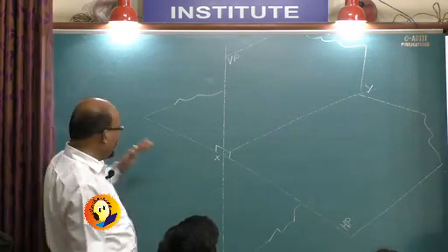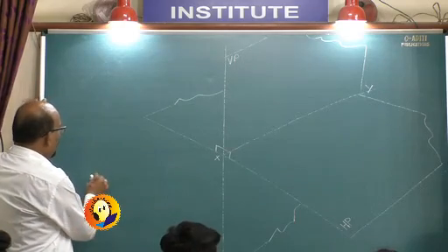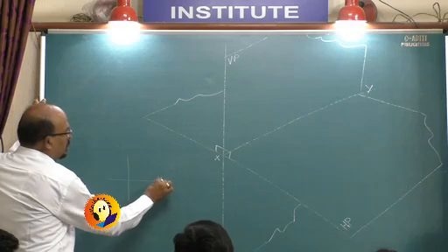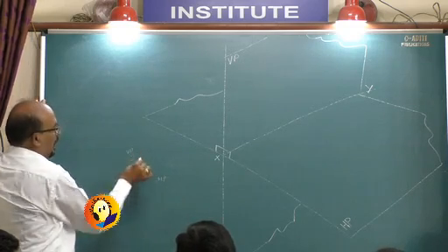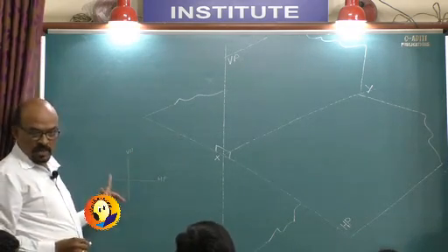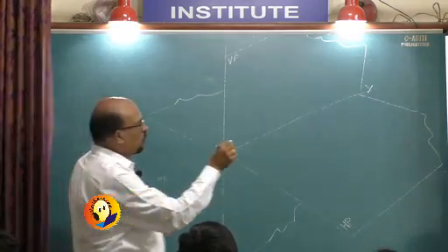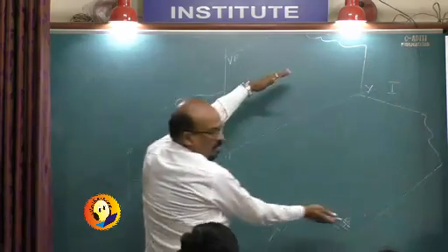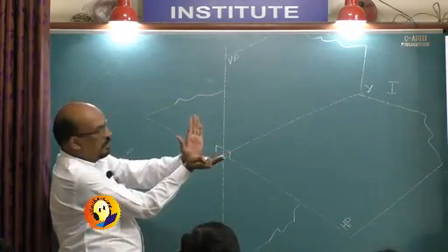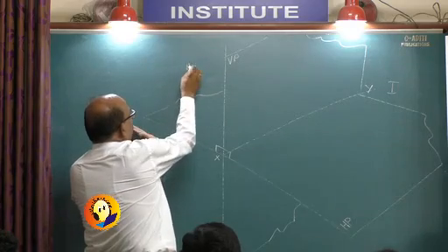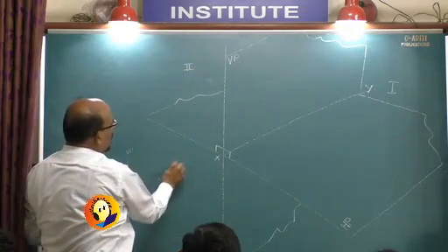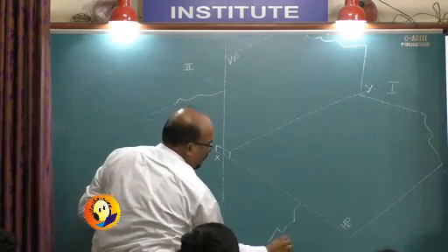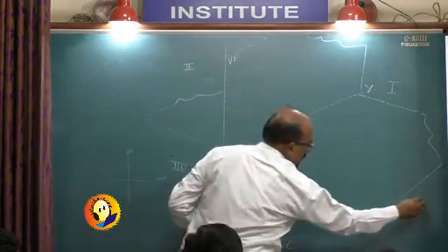Got this idea? So actually in 2D, if you try to look at it, you will find that these planes appear like this. This is HP and VP as I look from the left hand side. They are perpendicular. They are divided into 4 quadrants. This area is quadrant 1, this entire area between HP and VP. The second quadrant is this. This will be the third quadrant, and this is the fourth quadrant. And where are we? We are here.